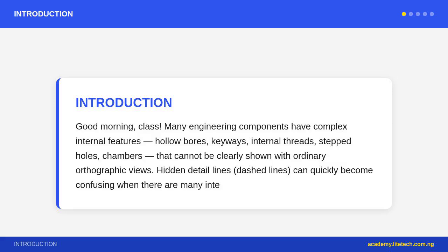A sectional view is obtained by imagining a cutting plane passing through the object, removing the near half, and looking at the cut surface. The cutting plane is shown on an adjacent view, usually the front view or plan, as a cutting plane line, a long dash, two short dashes, long dash line, with arrows indicating the direction of viewing.